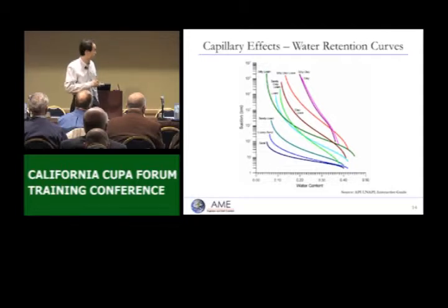Now, let's give an example here. This is a sand, and at this level, it's roughly equivalent to 5% water content in the pore space. And you have something like 100 centimeters, roughly 3 feet, which means if you have a box, a fish tank of sand, and you put in 5% pore space water, you're likely to see moisture rise about 3 feet, something like that.